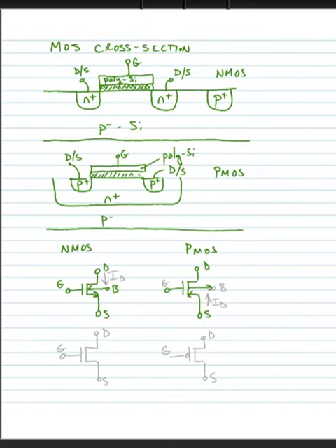And our bulk contact has an arrow coming out of the terminal. Or, for logic, oftentimes, because again the source and drain can be interchangeable, they don't mark the source or the drain, and they just use a generic symbol like so, or we put a bubble at the gate of the PMOS device to let us know that it's PMOS instead of NMOS.